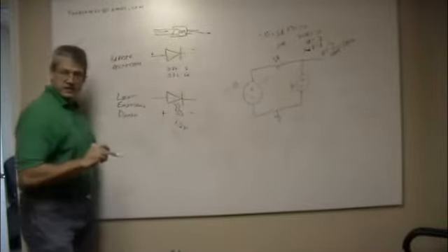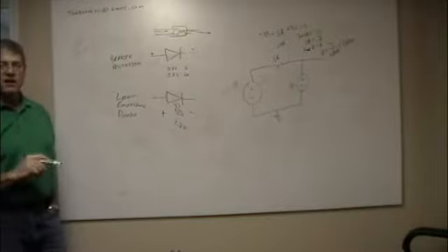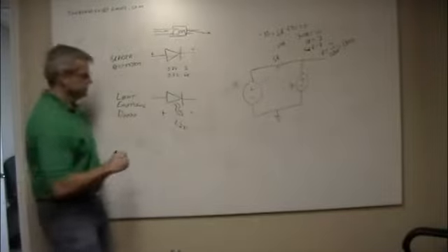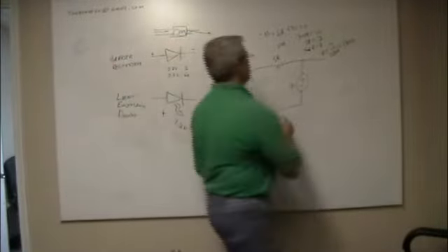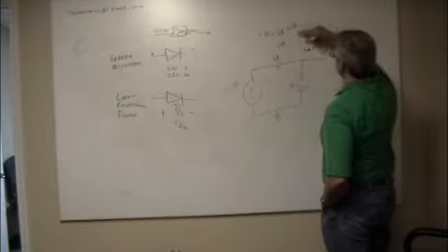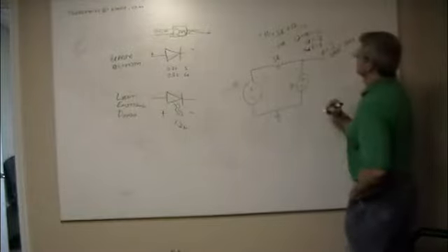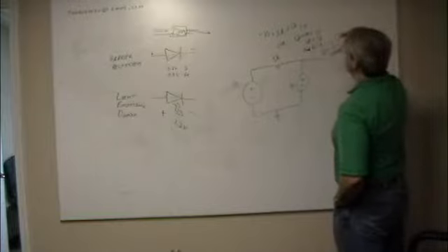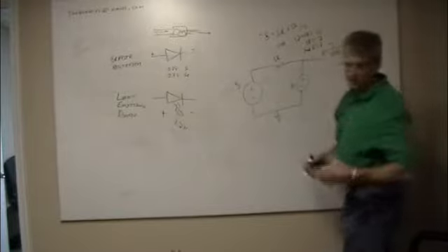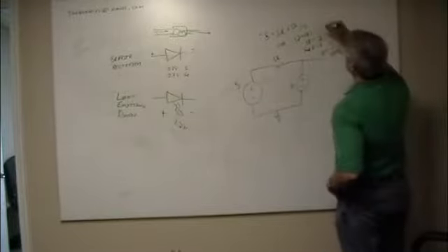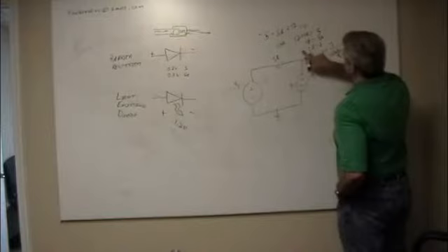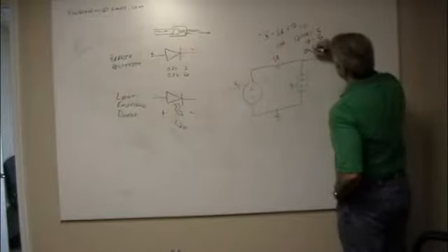So you have to put the ballast in, and most of them, their maximum brightness, it depends on what you look at, but they're like 15 or 20 milliamps. So again, we do the math, we'll say 20 milliamps. So 3 becomes 1.2, and let's make this 5 because we would normally have a 5-volt supply, right? Our Arduino uses 5 volts, the logic is 5 volts. 5 minus IR is 3.8, and now instead of 5 milliamps we've got 20 milliamps.